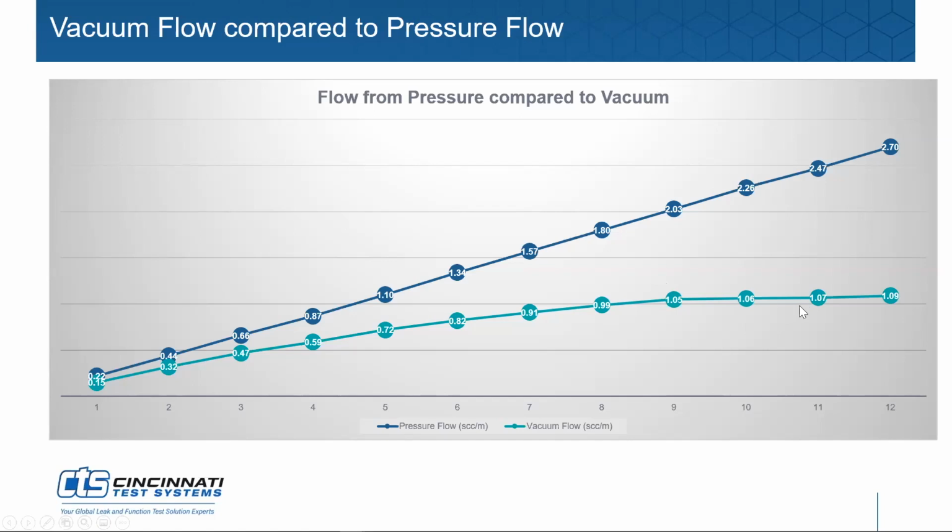So if you're testing for part stress under these vacuum levels, you can increase your vacuum level above 5 or 8 or 10 psiv. If you don't need to do that, then testing around 5 psiv seems to be the right place to stop when you correlate pressure to vacuum. And if you get to 15 psi, we're all in trouble.